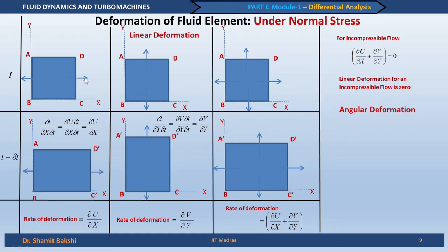on this surface, it is subjected to a normal stress, but if it is a square element and we take a diagonal of this fluid element, it will experience a shear. So, the normal stress can induce a shear in the fluid element, which you might be familiar with from our analysis of strength of materials, where we try to define the state of stress in a material using a Mohr circle.